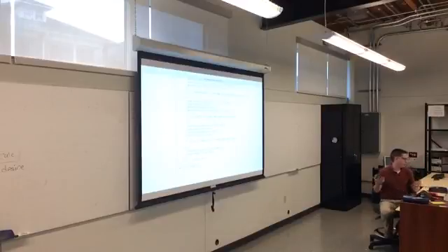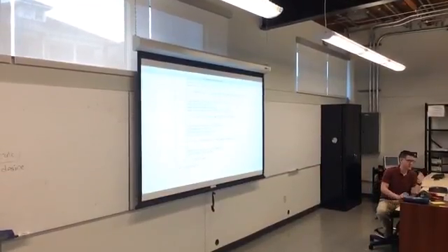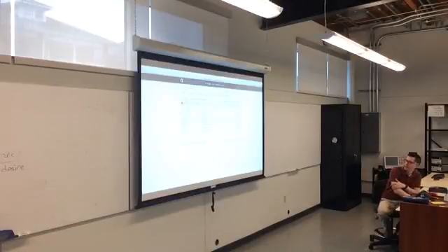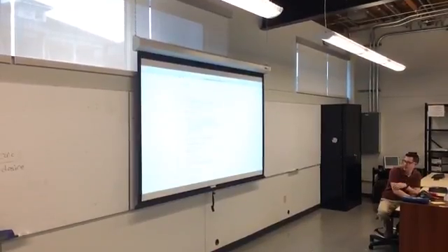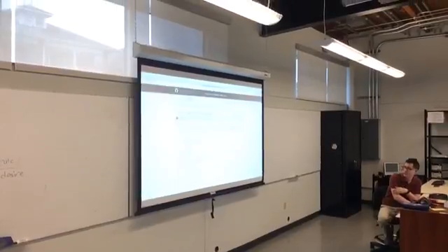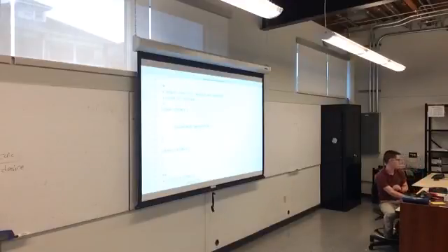The accelerometer, I have given you my code. You have my code here that does everything. This is my implementation of setup. This is my implementation of initialize. This is my implementation of everything else. What you'll notice is that in the constructor, it grabs a pointer to the I2C interface. Technically, it grabs a pointer to the custom I2C interface that you will use, and it grabs it as a singleton, which is statically allocated, so you're not going to be talking to multiple devices.